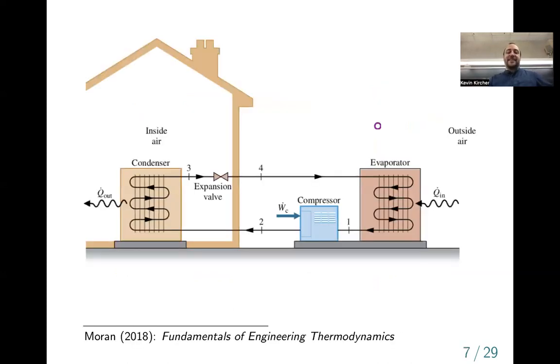All right. Anyway, so this is another schematic of what's called an air to air or an air source heat pump. So the components basically would be the compressor and one heat exchanger. The evaporator would be outside, and the other heat exchanger, the condenser, would be inside, and the expansion valve typically would be inside as well. Sometimes it may be outside. And yeah, a heat exchanger is a fancy way typically of saying pipes. It's just wiggly pipes with some fins on it to increase the heat transfer area.